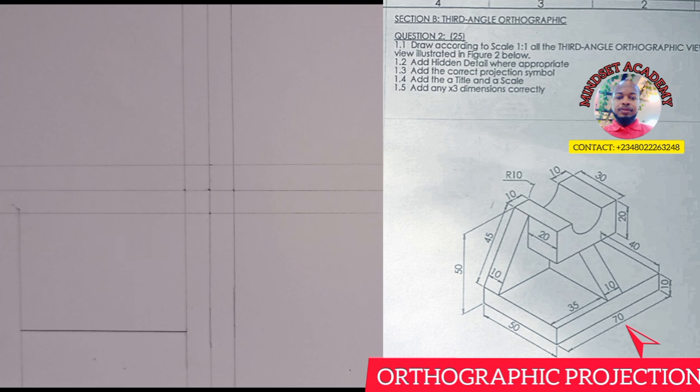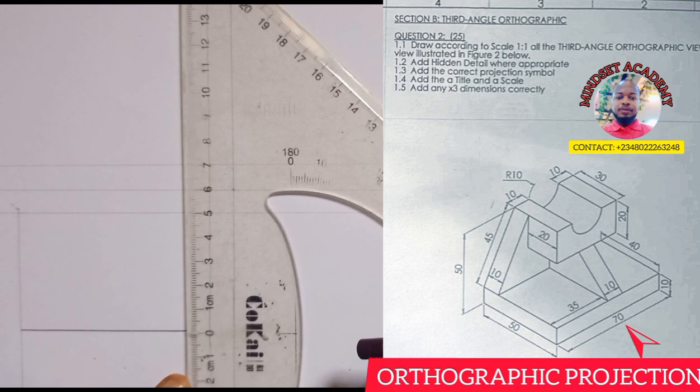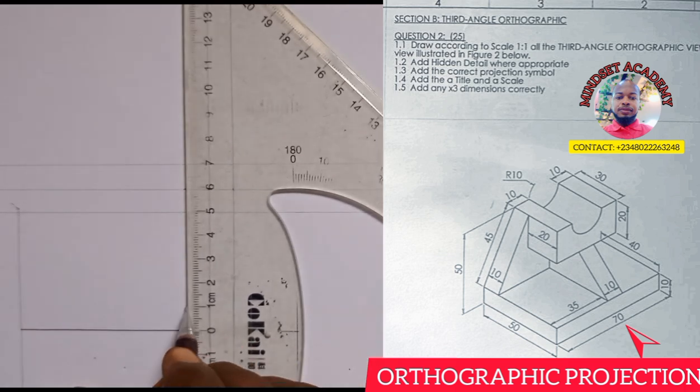If they say 1:1, it means use the same measurement as given. It's the full size. So 2:1 means twice full size, 1:1 means full size, 1:2 means half full size. So the thickness here is going to be 10. I'm going to measure 10 millimeter from here, from 0 to 10. It's 10 here, and just easily close it up.